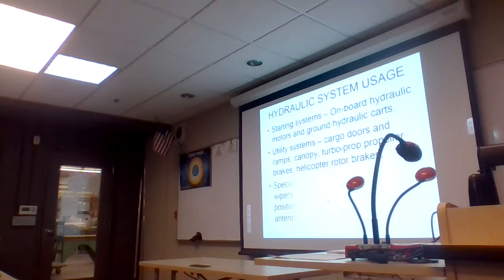We also use it for starting systems on some airplanes. Most of the Sikorsky aircraft start hydraulically. There's a reason for that. In order to motor the aircraft engine, sometimes it's more efficient to do it hydraulically than electrically. And it's self-contained in many cases. A lot of the Sikorsky aircraft have accumulators where storage of hydraulic fluid is possible. We release that fluid into a hydraulic motor in order to start the APU for the aircraft, and then during start, the accumulator is recharged again. So that's how it should work.